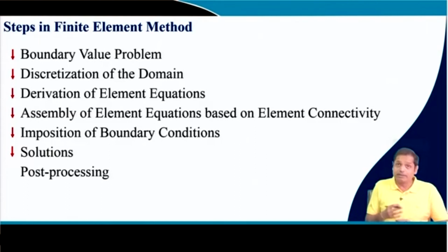Once the element equations are written, we need to assemble those equations to get the global equations, and this assembling has to be done based on the element connectivity, how the elements are connected with each other. Then once we have the global equation, imposition of boundary conditions, and then final solution, and then of course postprocessing. Once we have the solution, how to visualize the solution, how to extract other information from the analysis.